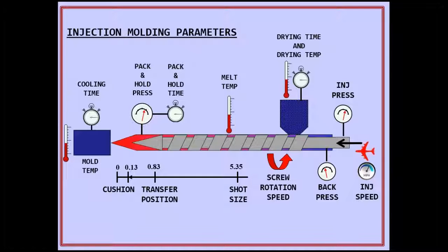Melt or mold, cooling time, holding pressure. You can go into pack and hold again. The difference is written on my website. Please read that. And once you play with this stuff, give these samples to your molder. Don't spend too much time. Or they say, you know what, these are the highs and lows of all these things. This is the best we can do. And I'll tell you, that's the reason people have orphan tools in their shops, because some other molder is not able to run them, right?